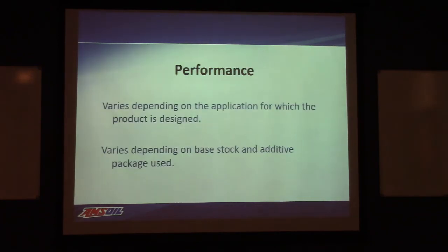So, a couple of final thoughts on it. We talked about performance is going to vary depending on the application for which the product was actually directed and formulated. And also, performance is going to vary depending on the base stock and the additive package. Not only type of additive, but quantity of additive.